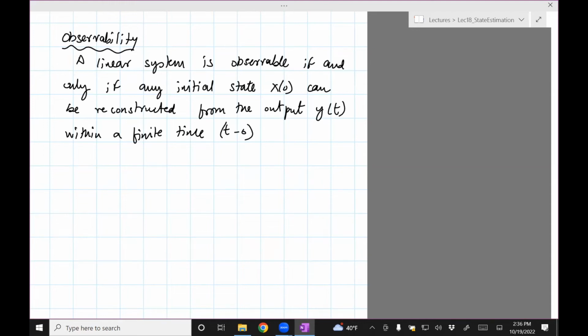That is, if you don't have those types of measurements, then you are not able to estimate those states. So for example, in this case, if you only have measurements for the positions and velocities of one mass, then you probably cannot estimate the position and velocity of the other mass. Now that's probably not true here because the system is coupled, so moving one moves the other.